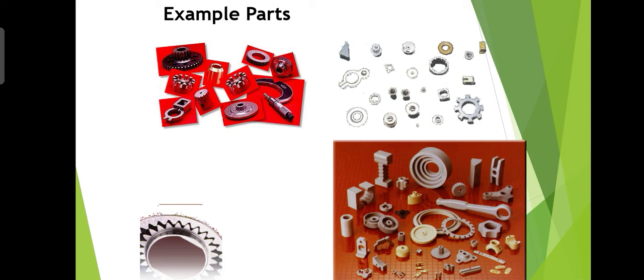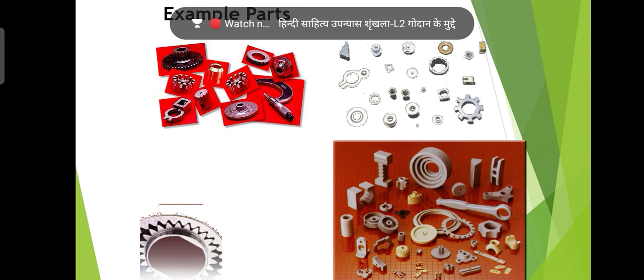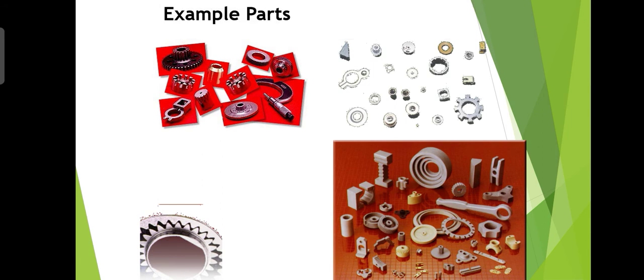If we are going to talk about the basic steps of powder metallurgy, then raw materials are prepared and mixed. Raw materials are elemental or alloy metal powders and additives, if you want additives: graphite, dye, lubricant. These are some additives that will be mixed in the powder. After that the mixing process will be done, and then the forming process, hot compaction and cold compaction.